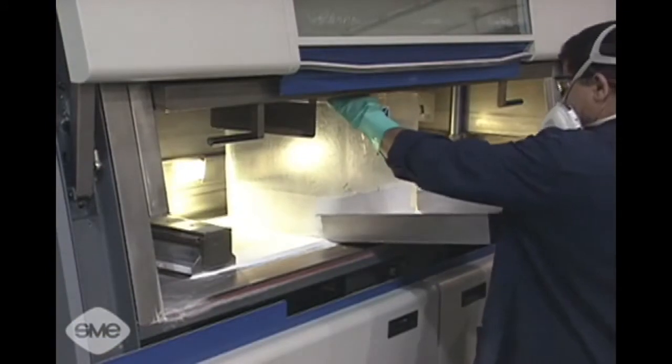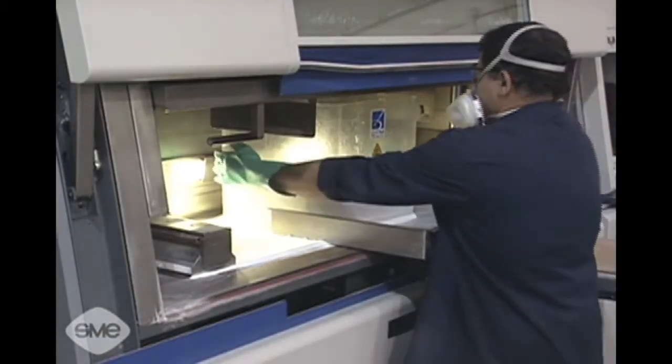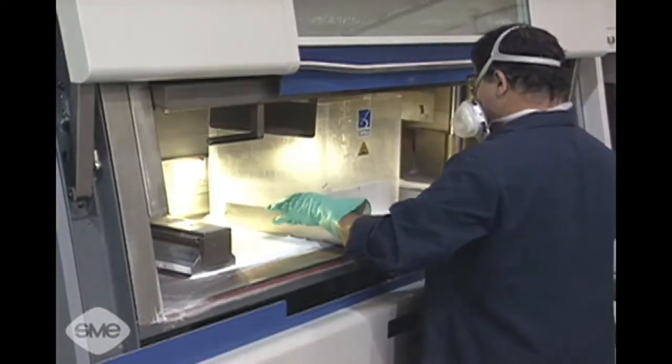The laser beam scans the model design according to the CAD file and selectively sinters or fuses the powder particles together. The model platform lowers incrementally as each successive layer of powder is similarly fused. Once complete, the model or models are moved from the machine in a cake of unsintered powder.